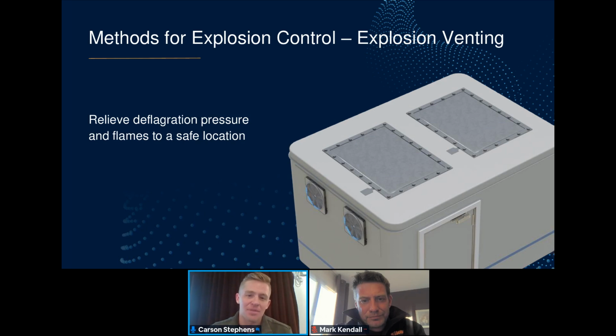And what I mean by the opposite is it's essentially a piece of stainless steel that's bolted onto your enclosure, like we've kind of shown here, that's set to burst at a predefined burst pressure that's been tested. And if you have an explosion, the doors open. That's essentially what an explosion vent is. It's used in so many applications I don't have time to go through today, but this is another one that it's being used for. But think of it as your safety net.